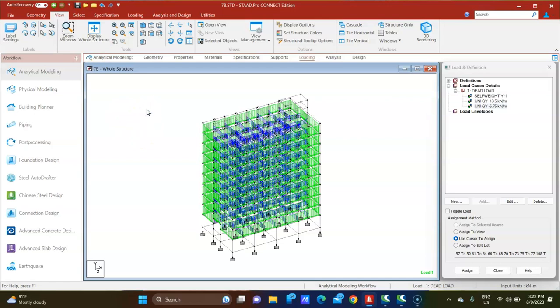Okay. So if you see, intentionally I left the roof because parapet height is something different, right? Generally by practice parapet height is 0.75 meter or 0.7. So I am considering the height of the parapet is 1 meter.